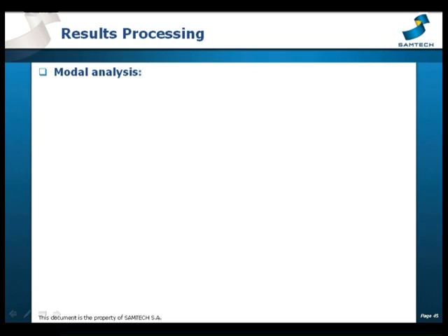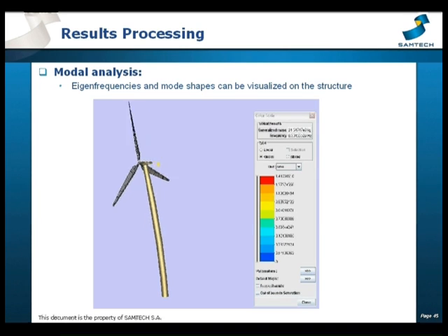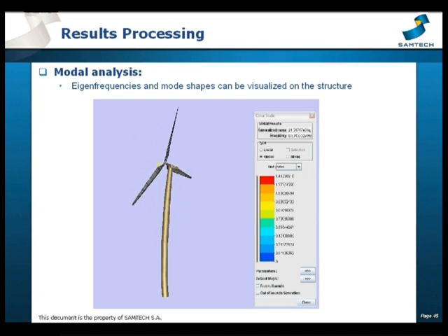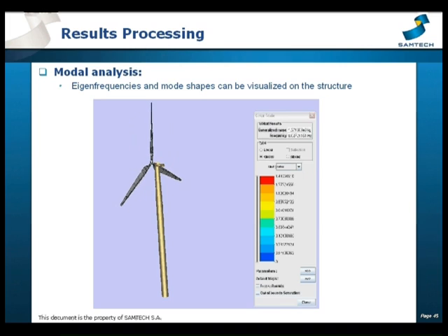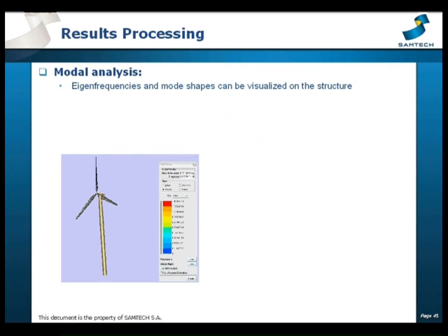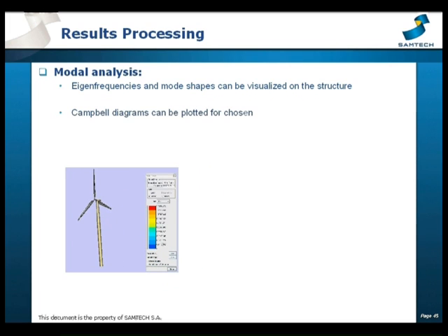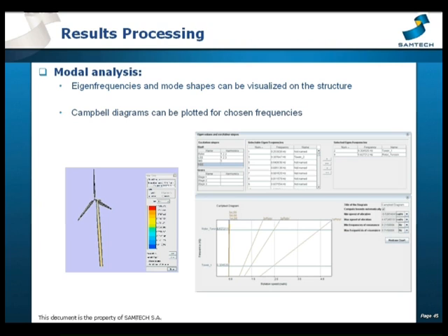Modal analysis post-processing is also quite straightforward. The user can see the list of eigenfrequencies and animate the corresponding modes on the structure. Campbell diagrams can also be plotted to calculate dangerous rotation speeds for each component in order to avoid resonances.